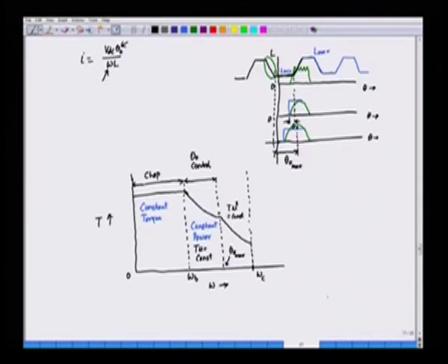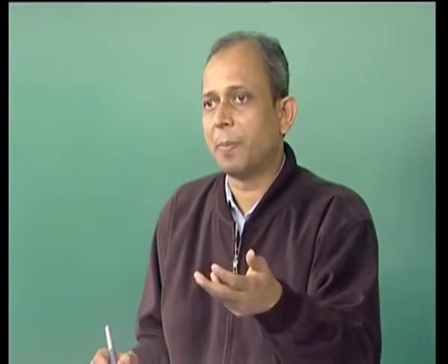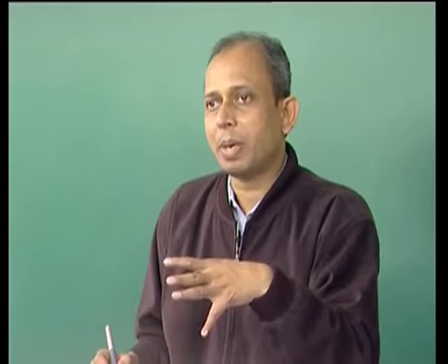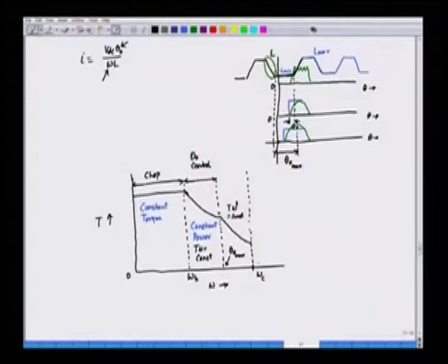Beyond this speed, the machine will not run, because the bearings etc. will begin to fail. This is limited by the mechanical constraint of the machine. So, the machine has been designed for a maximum mechanical speed. Beyond this, the machine will not operate. So, this is the critical speed. So, we have 3 different modes here: the constant torque mode, the constant power mode, and T omega square constant mode.